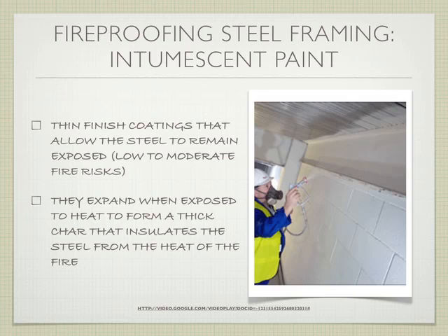So if we were in a building that was a hospital, we'd be far more concerned with fireproofing than something smaller like a grocery store. Because it's easier for people to get out of a single-story or two-story building than somebody in a hospital bed who needs help to get out. So whether this is allowed will vary depending on the type of building.